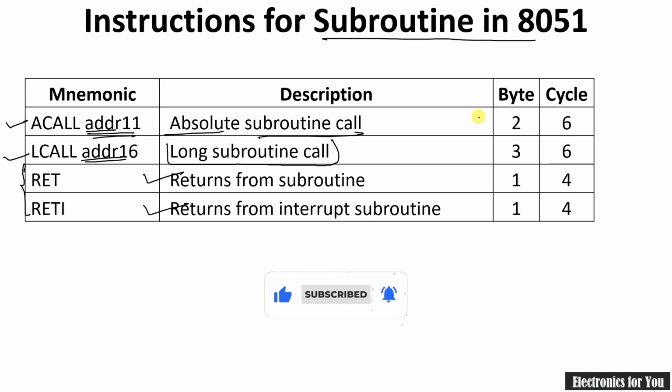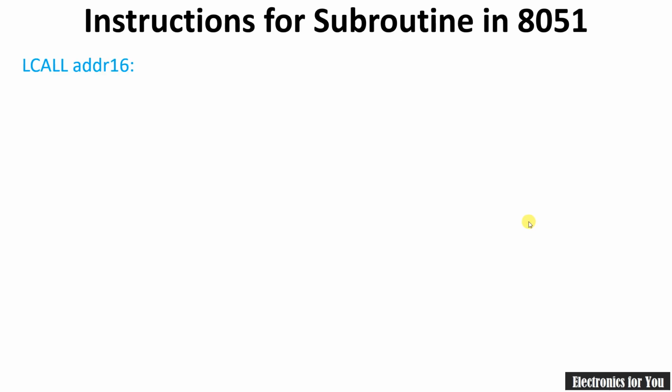Note here that the memory byte required for ACALL is 2, whereas for LCALL it is 3, and in case of the return instruction only 1-byte instructions are available. So let us start with the first and simple one, that is the LCALL address 16. We can write an example just like this: LCALL 5000H.